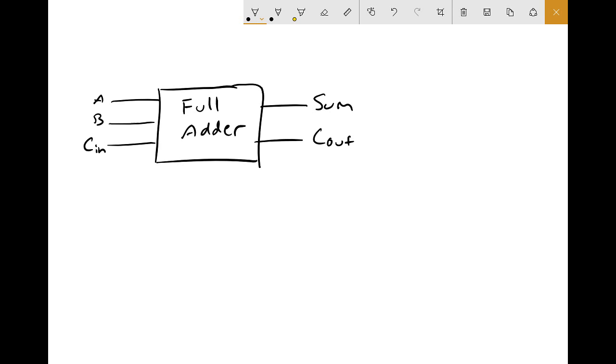Let's go back to our full adder circuit, and let's put that combinational logic block into a box, and just imagine that this is a black box that implements the full adder logic that we've already seen. Now, you may have been wondering when we drew this combinational circuit, why is there an initial carry in? If you were to study a little bit about the 2's complement binary system, you would see the way that negative numbers are implemented using binary bits. There's another important reason for this carry in being part of the full adder input.